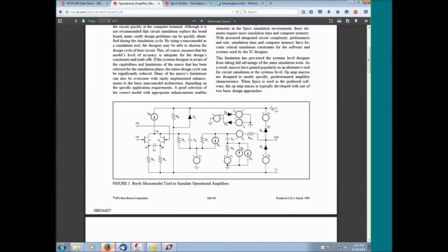The reason we model and the reason we simulate is that usually we don't need a super exact answer. An answer that's within 1% is more than good enough. And with the quality of simulations today, you can actually get much better than that. But if you had to calculate all of the node equations for all of those transistors in that LM741 schematic, as you can see in a data sheet, for example, the amount of time it would take is just not practical.